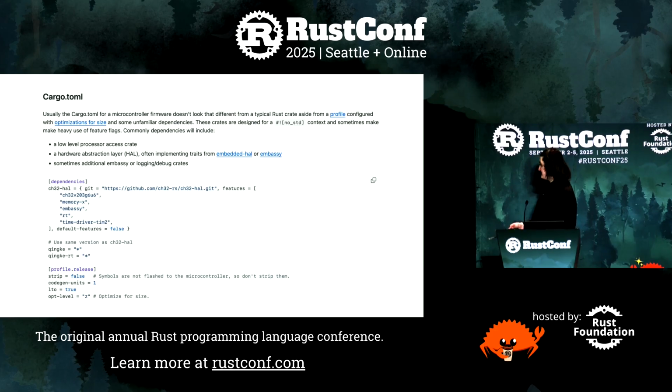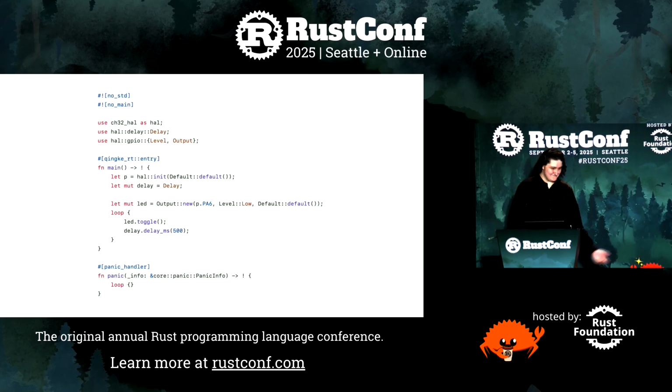And then this last little bit I'll give a shout out to is essentially just the recommendations from min-sized-rust, which is kind of the Bible in terms of embedded programming. You need your code to fit inside of the flash that's available. And so we just minimize the size with some things to tell our compiler. Okay, and then next, that's a Rust program. This runs, and this is the kind of worst case scenario for a hello world.